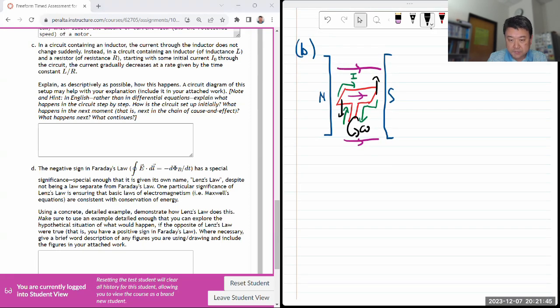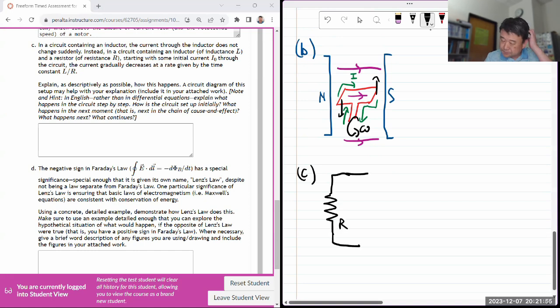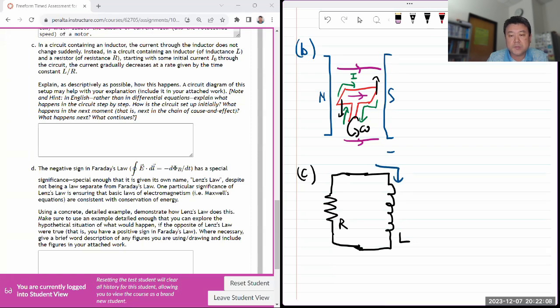So you can imagine a setup like this, where you have a resistor, because everything has a resistor, and not having a resistor will make your model somewhat impractical. And you have an inductor that's all connected. Let's say you found yourself in some situation where some amount of current I naught was flowing. Then this is what you want to think through. This current is flowing through here, which means there will be a voltage delta V here that comes from current times resistance. Because of the way it's connected, it's the same voltage across the inductor here.